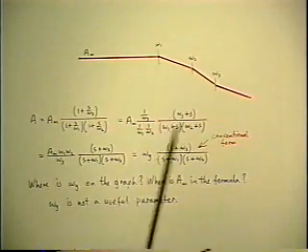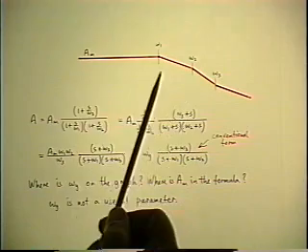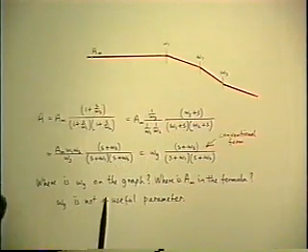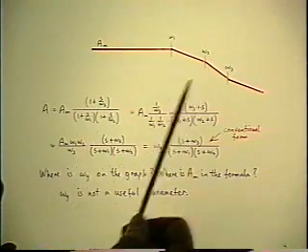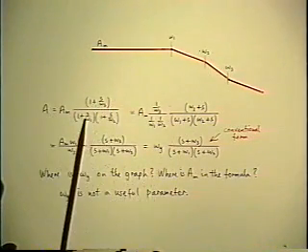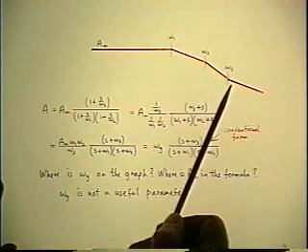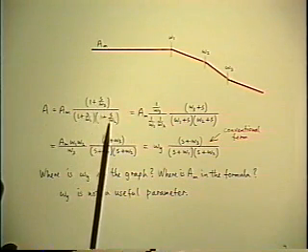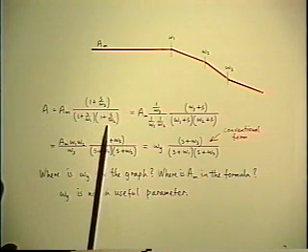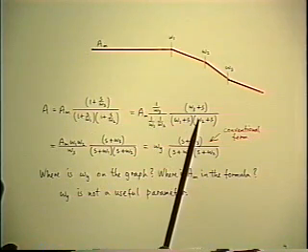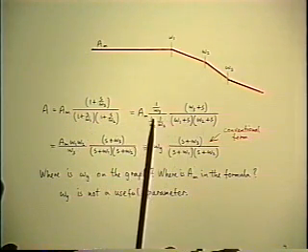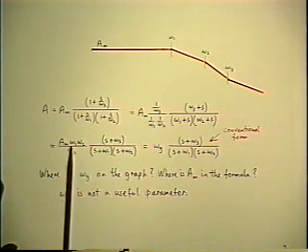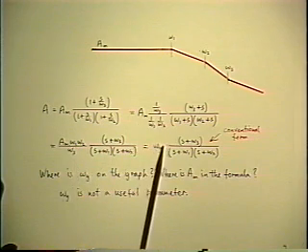Look at this example, also one of the ones we had earlier. This is the one I recommended, where you write directly from looking at the asymptote graph, A equals AM, and then two normal poles followed by a normal zero. But now suppose you don't like even this format, which is sort of using normalized frequency. Suppose you want it in the format on the right. That's easy to get. And once again, all you have to do is bring out some terms in front, collect them together, and define a new parameter.